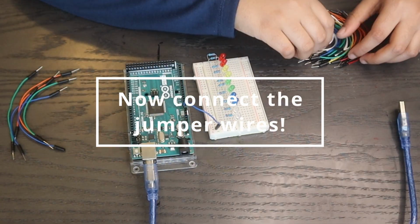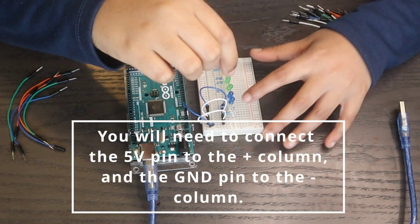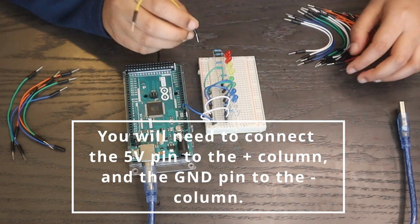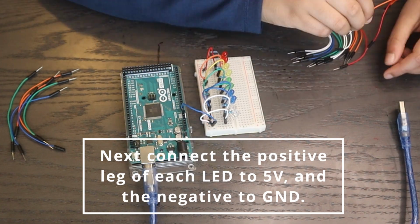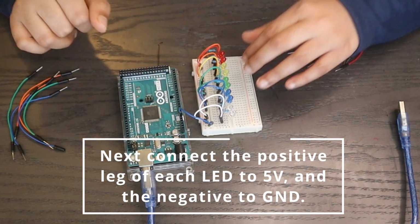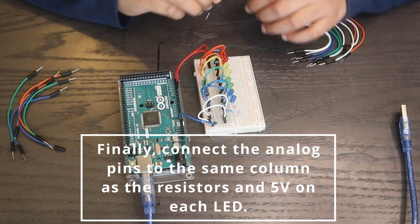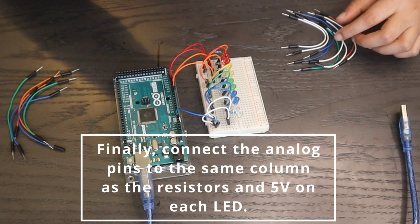Now, connect the jumper wires. You will need to connect the 5V pin to the positive column and the ground pin to the negative column. Next, connect the positive leg of each LED to 5V and the negative to ground. Finally, connect the analog pins to the same column as the resistors and 5V on each LED.